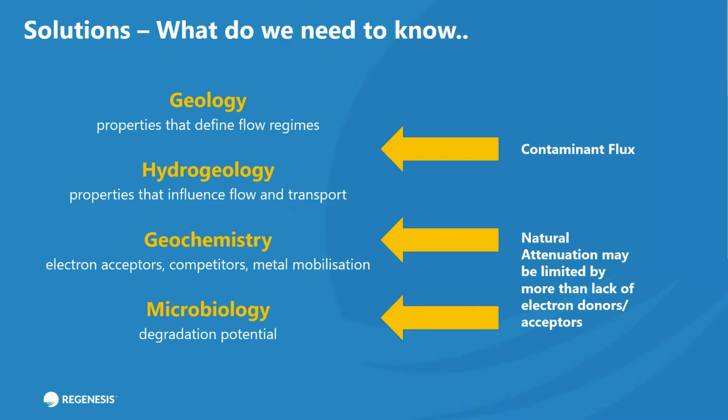It could be that you have very high flow of groundwater moving through this system, so you're getting lots of aerobic water that is inhibiting that reductive dechlorination process. It could well be that you're dealing with quite a barren system, so there isn't much micronutrients down there. So that could be in the form of, if we're sticking with the chlorinated solvent theme, electron donors. It may be that they are lacking in micronutrients such as B12 and other dissolved metals.